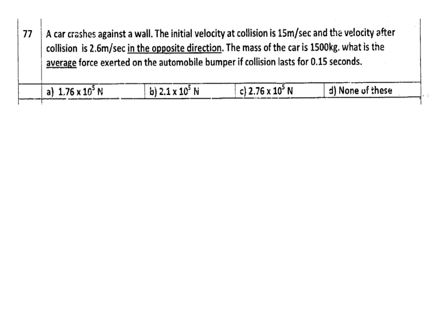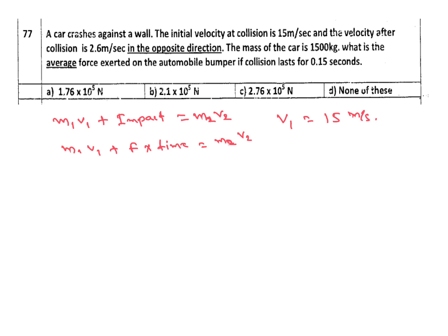Initial momentum plus impulse equal to final momentum. M1 V1 plus force into time equals M2 V2. From here, initial velocity is 15 meter per second. Mass M1 equal to M2, both are same, 1500 kg.